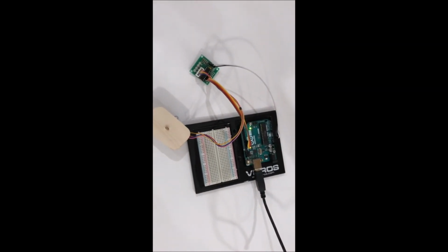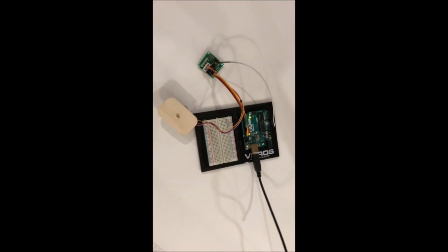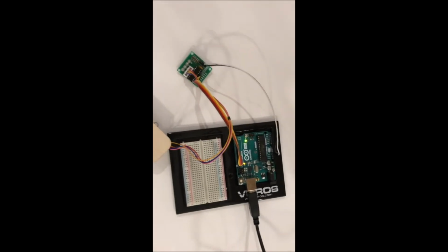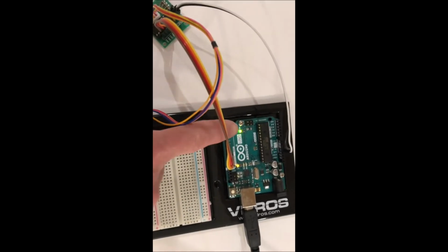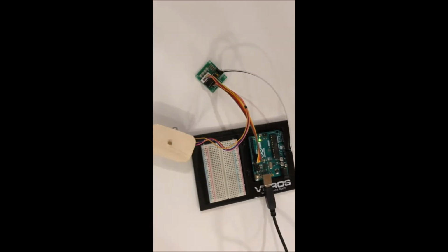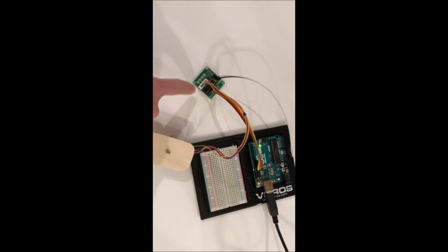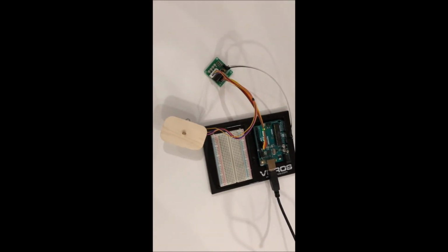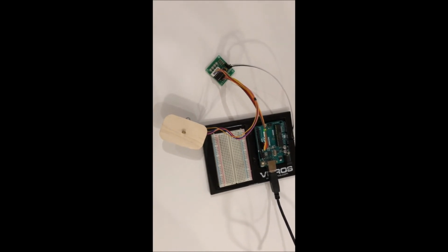All right. Is it connected to the Arduino? Well, let's look up here. Yes, I'm connected to the Arduino. Okay, that's not the problem. There's a light on the Arduino, so there's no shorts. Well, when I look on my Arduino, I can see that there's power getting to the Arduino board. And in fact, when I ran it, I could see that there were lights lighting up on this board, so I know that there was power getting all the way to the stepper.